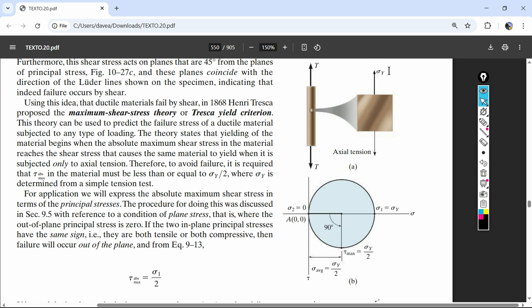And so you don't pick up any shear. Also, let's say this is 10, and then this is 5. Then your Mohr circle, that's the diameter, your Mohr circle is smaller, and that's your max tension. But if this is 10, and this is negative 10, negative 10's over here, that's going to be the second principal stress, because it's smaller, and our circle is going to be out here. That means that their shear is going to be twice.